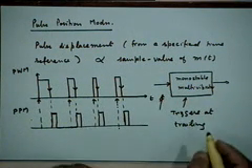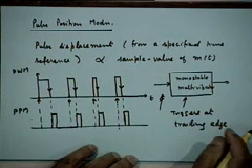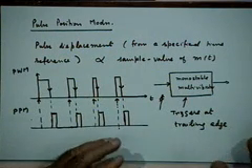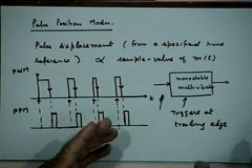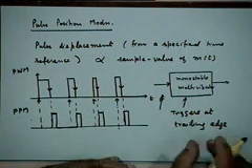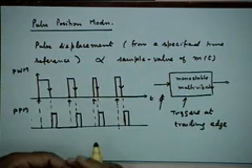But in PPM, once I have a pulse having some width, and I have no information from that pulse except for the position of it, you can either have an impulse at that point. Impulses are very difficult to handle. They will have very large bandwidth. That is why you always go for finite width pulses. The moment you have finite width pulses, you are actually reducing the bandwidth requirement, right? Isn't it?